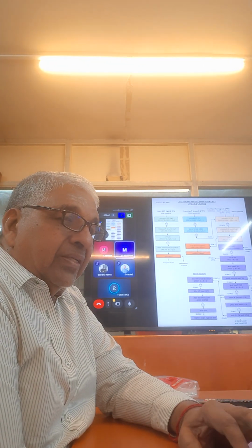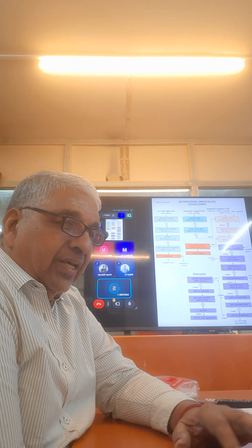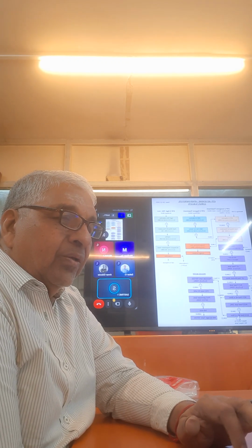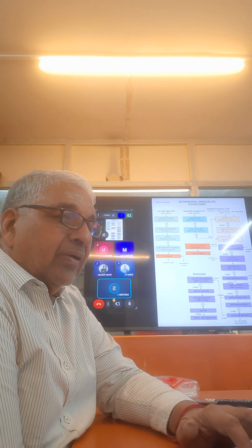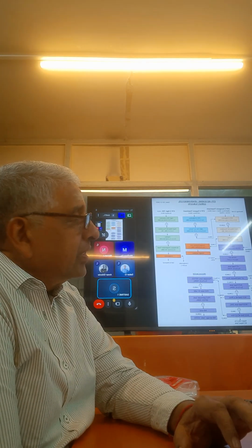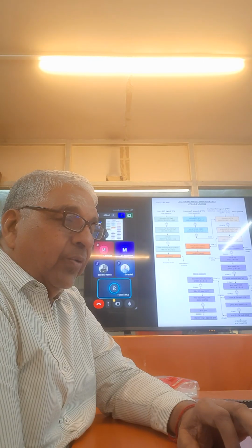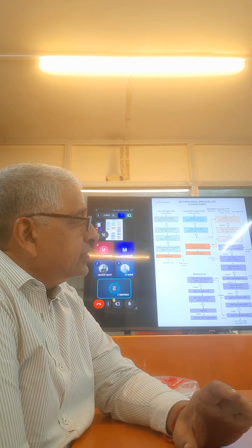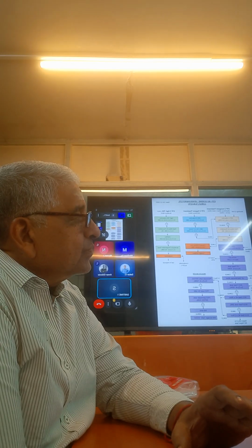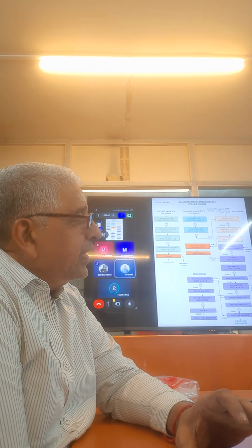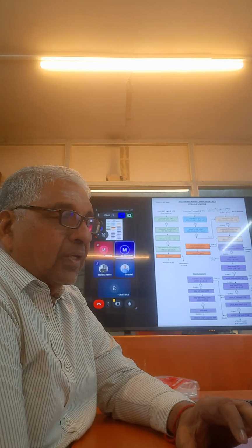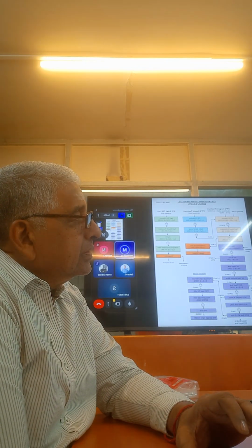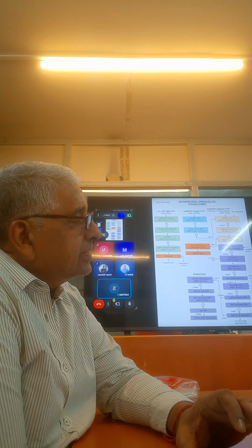Now we can straight away have a third stage here, or my suggestion would be to use the evaporator first. It will take at least one year for you to get this fully operational. Then we can see the capacity, how it performs, everything, and then we can go for a third stage. Yeah, correct. Only the space planning can be done as a constraint. We can provide space and have the evaporator. Later on, we can add RO, and then the evaporator will be more efficient. Yes, correct, wonderful.